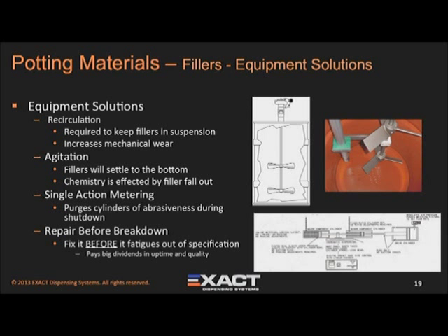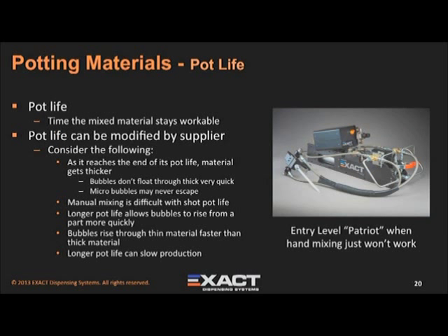It is also critically important to start a repair before breakdown protocol that allows you to keep up production and maintain quality. Pot life is another material feature that has a big impact on your application solution. Pot life is basically the amount of time a mixed material remains workable in your product or process. You need to remember that as the pot life time is used, the material is constantly changing viscosity.